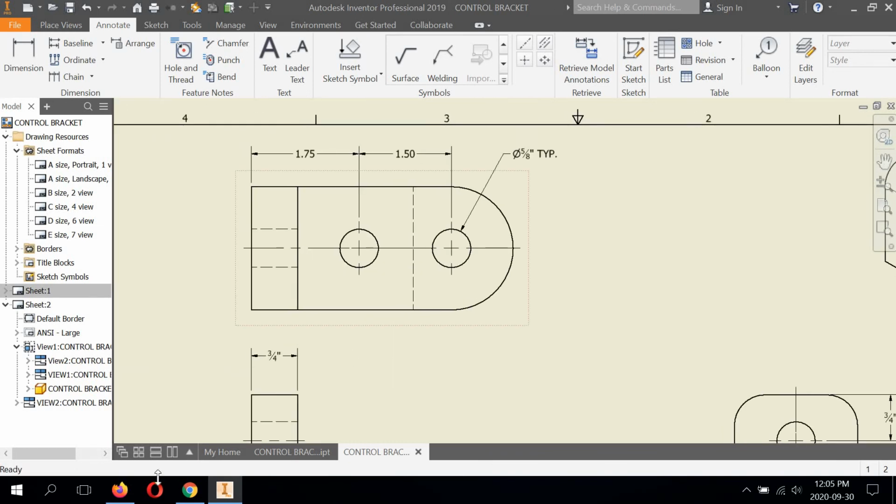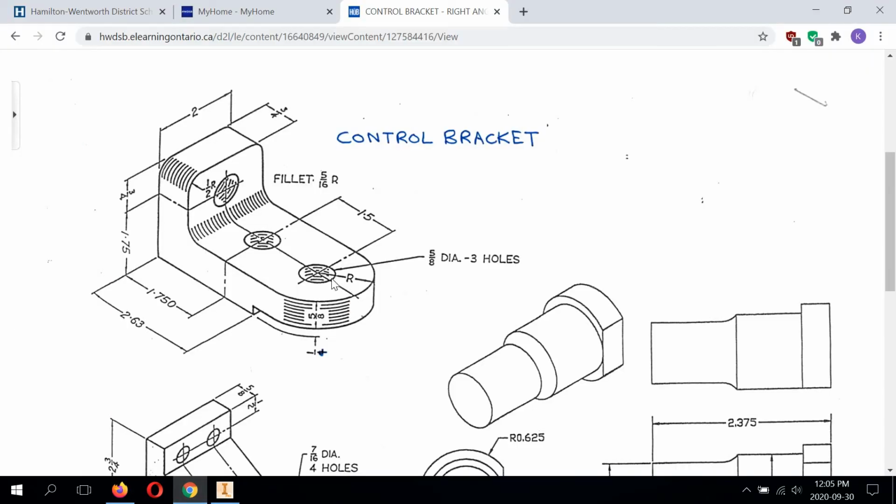We also have to identify this radius value here. And we're going to have to do this off of the part, off of the view. This 5/8 here, it sits right on top of the front or the right side view, depending on where you think it is, because it's a radius here. But we always want to pull all the dimensions off of the view.